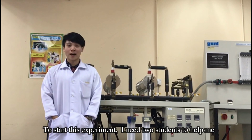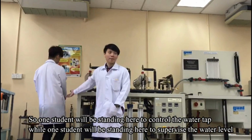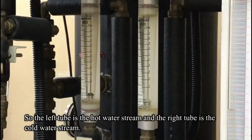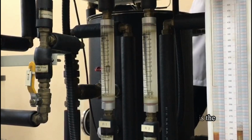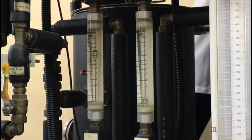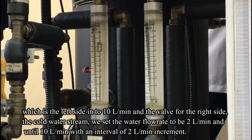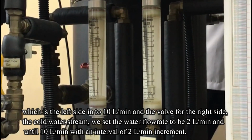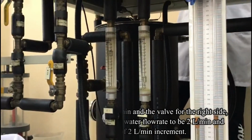To start this experiment, I need two students to help me. One student will be standing over here to control the water tap, and one student will be standing over here to supervise the water level. The left tube is the hot water stream and the right tube is the cold water stream. In this experiment, we fix the hot water stream, the left side, at 10 liters per minute, while for the right side, the cold water stream, we set the water flow rate from 2 liters per minute up to 10 liters per minute, with an interval of 2 liters per minute increment.